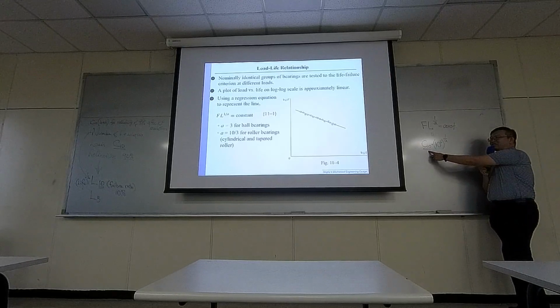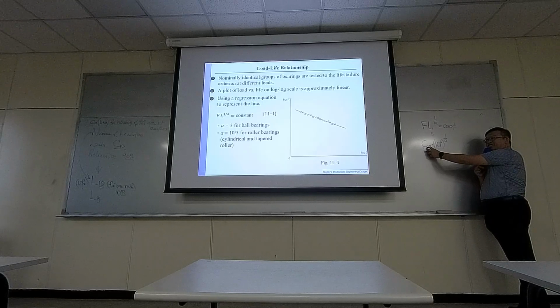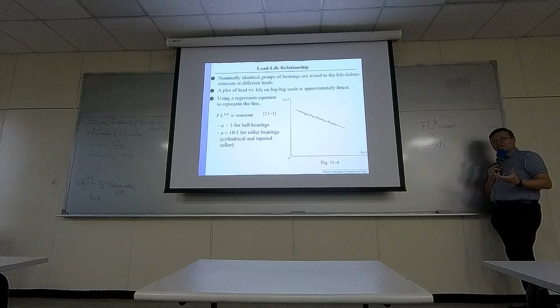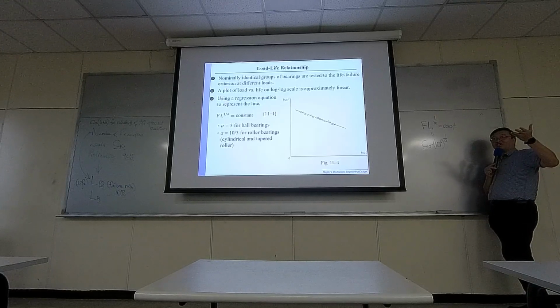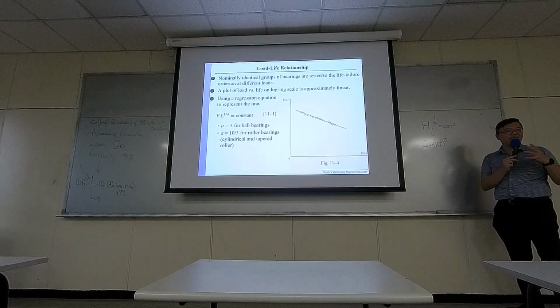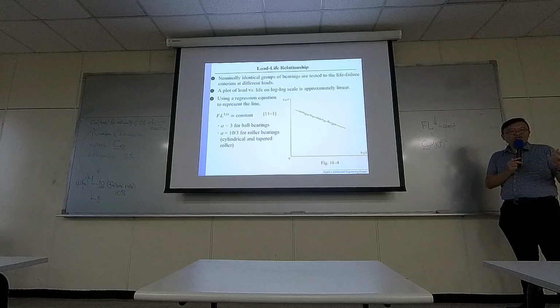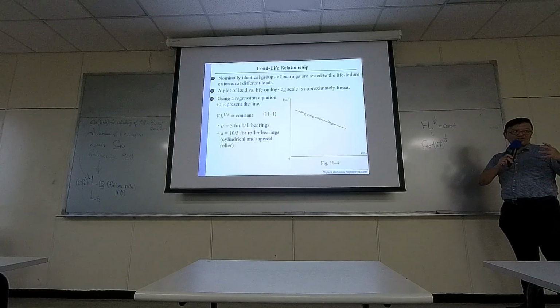Originally, maybe you choose one bearing with a certain amount of C10, and you realize that is not enough. Then you may need to upgrade the design to a stronger one. But when you do that, sometimes the dimension changes, because if you are looking for a stronger bearing, of course it's going to be bulkier.